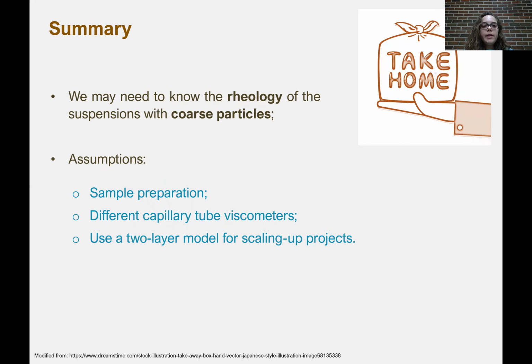So, talking about the summary, in today's mini lecture we learned that we may need to know the rheology of suspensions with coarse particles. And according to Fulham's work, we can do that using a capillary viscometer if we follow a few assumptions. Don't forget about that. Overall, your sample has to be previously classified. Your capillary tubes used should be 10 times larger than the coarser particle diameter, and try to use at least 2 different capillary tubes. I know you probably want to skip to the next video, but I want to draw a few comments on those points.